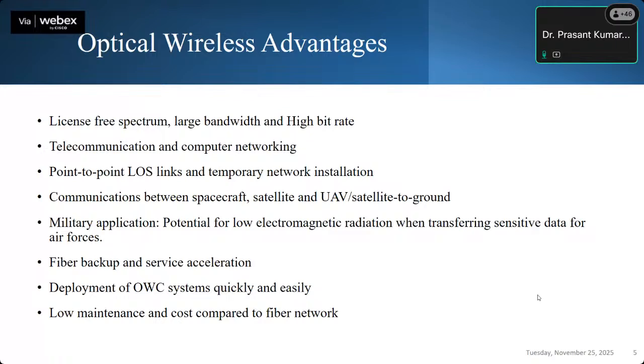So the person who tries to eavesdrop on these signals will only see noise, because the chaos basically carries no information. It is a chaotic signal generated using semiconductor laser diodes, which you directly modulate using your chaos signals.